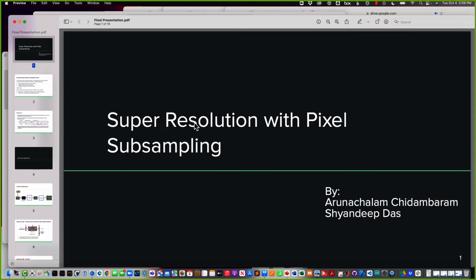So in any case, super resolution refers to getting more resolution than what you had sampled with, okay? And these guys explored some methods. This is where some of the work in deep neural networks using so-called generative GANs has been used. These two students explored that. Using these kinds of ideas, there are papers showing that you do sub-Nyquist sampling, but if you know it is human speech, then you can still recover it. Namely, you can unalias the signal. Okay, aliasing happened, but you can undo the aliasing, for example.